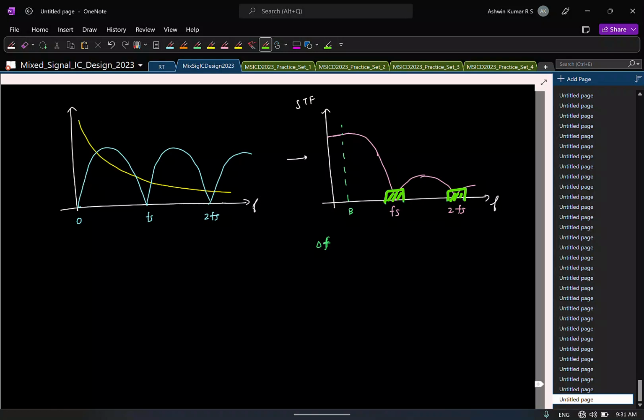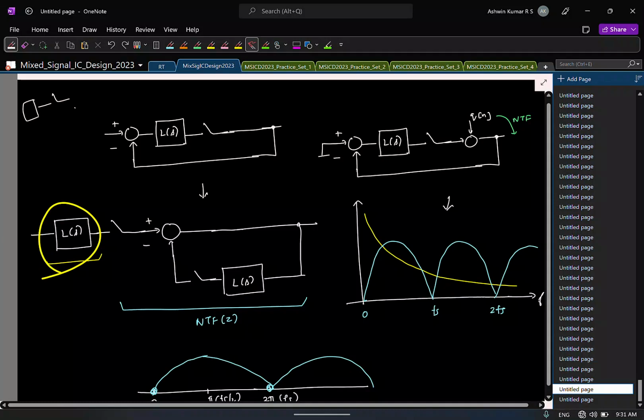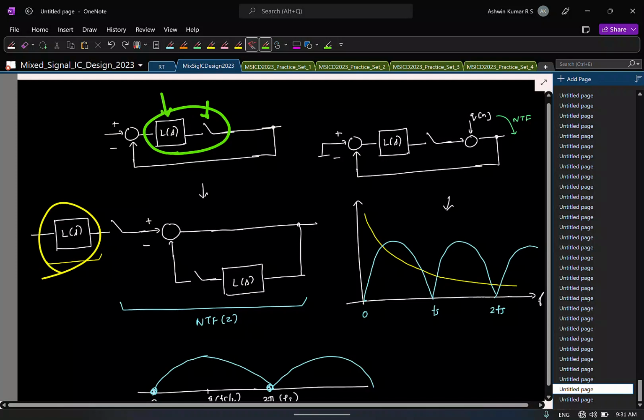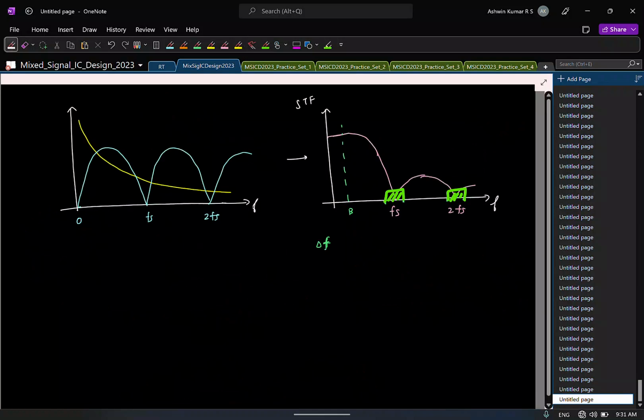Right? That's simply because, loosely speaking, in our circuit here, usually we sample it, and only to prevent aliasing we should have a filter before, and looks like that is already done here, right? Before sampling we do have some kind of continuous time filter, right? That's why it sort of helps us. So this is usually called the implicit anti-aliasing property of continuous time delta sigma modulators.